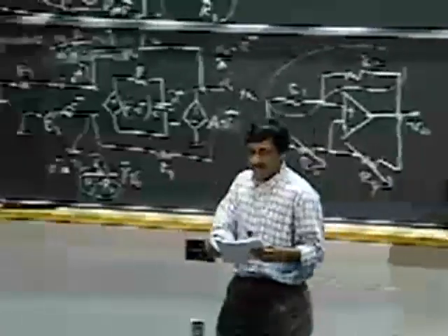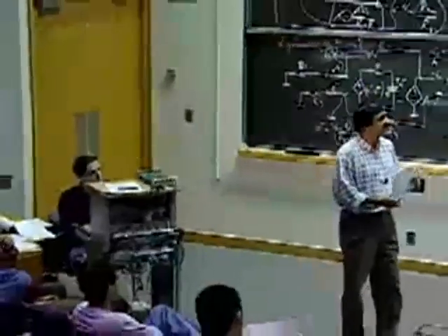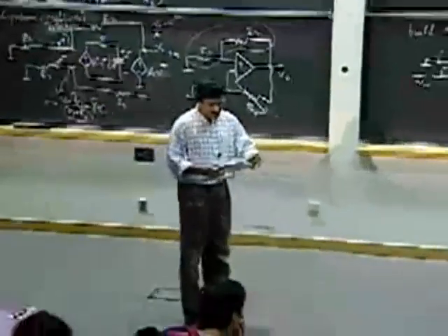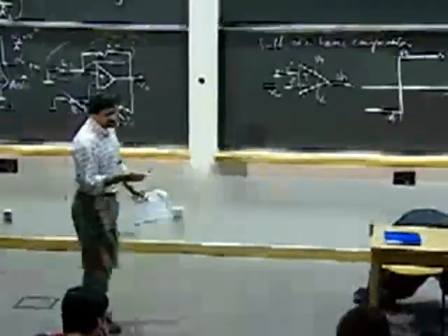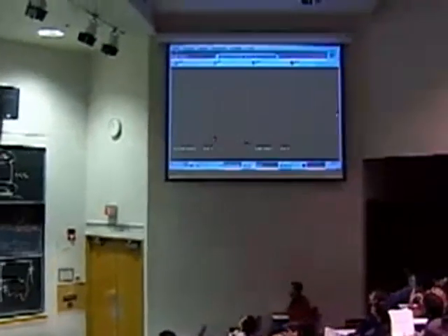In the last 30 seconds, let me show you a quick demo. Based on this property of hysteresis, I've actually built a little circuit. Notice here that I'm showing you the input on the x-axis, Vi, and Vo on the y-axis. Notice how the output switches at plus 6 volts, and then switches at minus 6 volts to plus 12 or minus 12. That's the hysteresis property.